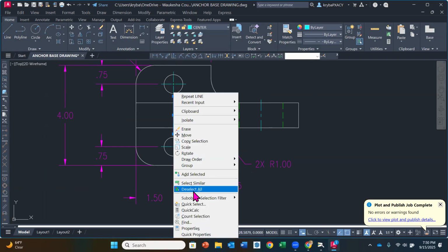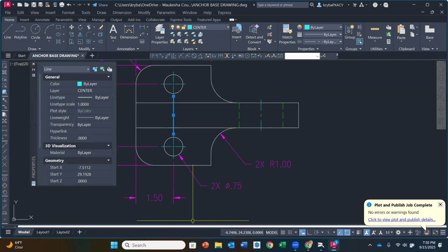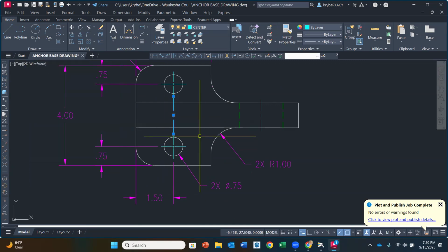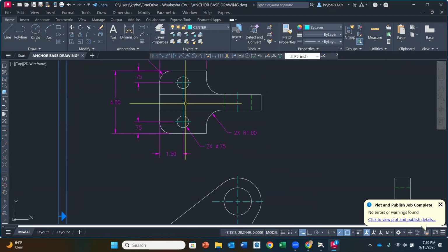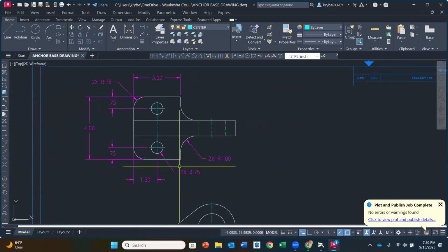I'm going to right click and just do the properties on that one line. And line type scale, I'm going to change that to 0.5. And it looks like it corrected it. Okay. It has that dash in the middle now. Okay. All right. So make sure that you see a dash there. And if you have to change that line type scale, go ahead. All right, so that looks like those are all the dimensions I need in my top view.